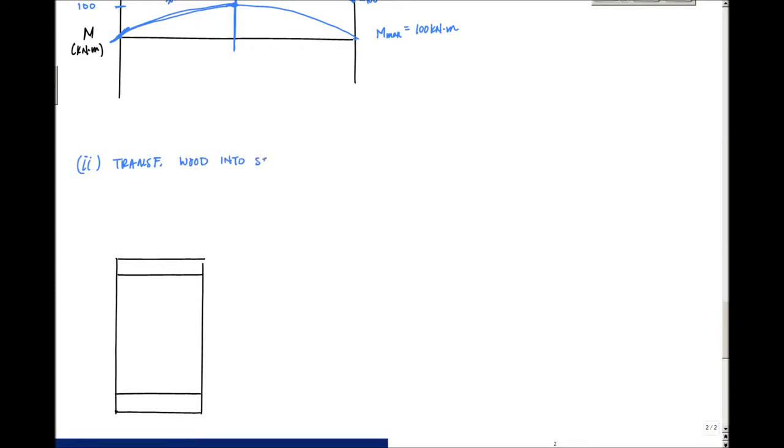And you know, and I know that if you looked at the composites overview and the composites transformed area video, then you know that you can't change the height because that changes your strain profile and that just messes up your anchor, if you will, or whatever your basis is for everything. But what you can change is the width because you need to change the area to satisfy force equilibrium or just have the same force.